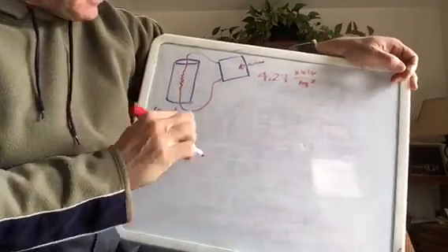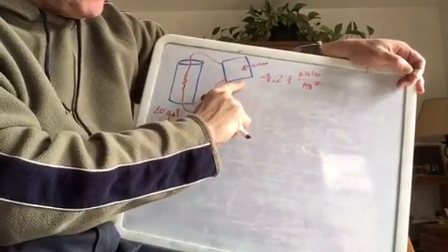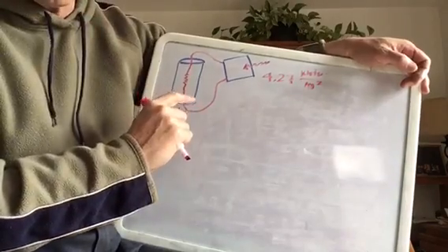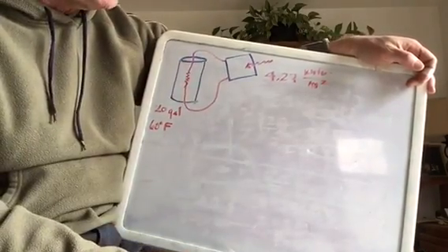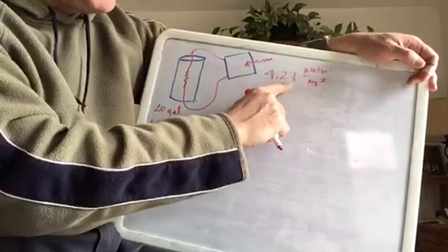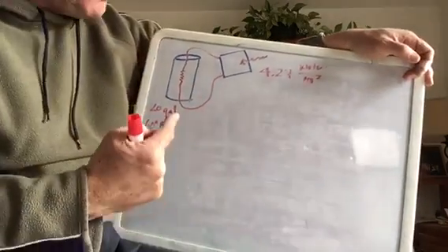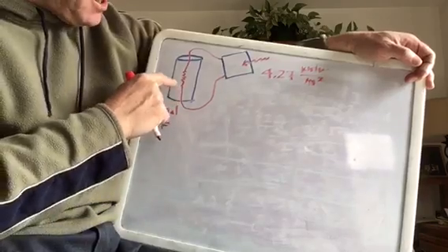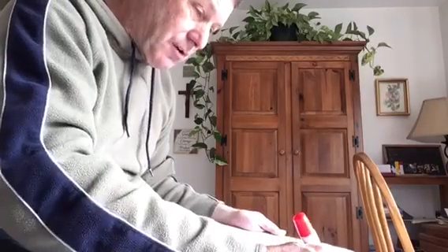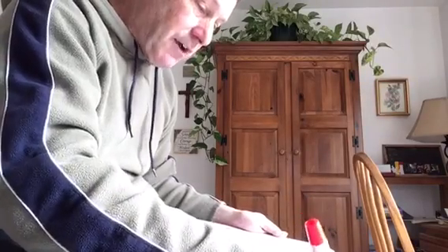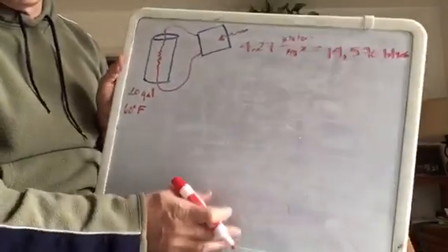So how's that going to work out if we had a meter squared panel and we actually tried to put the energy in there? Well, you can do the conversions yourself if you want to pause and try it out yourself and check my work. What I would encourage you to do is convert this to BTUs, because we know how to figure out energy change or temperature change of water if we have BTUs. I did that downstairs myself before I started this video, and I got 14,570 BTUs. So that's sounding pretty good. That's a lot of energy, okay? A lot of energy that's hitting that panel.